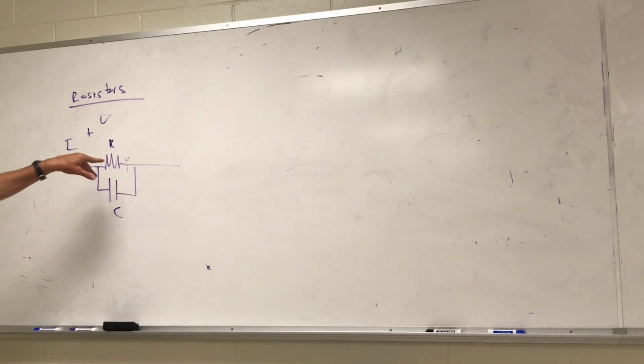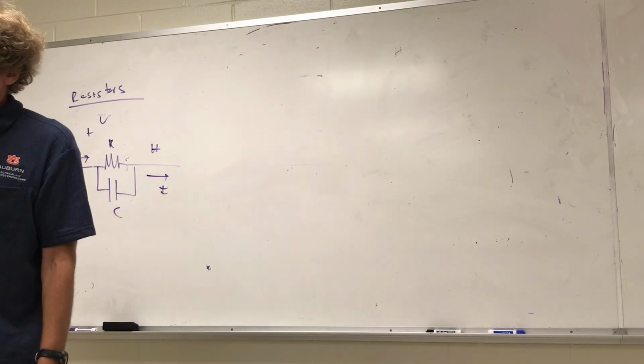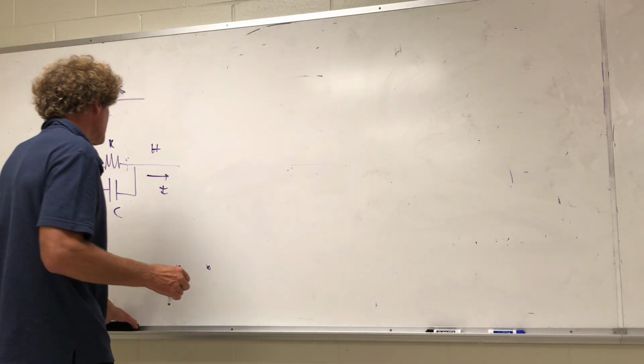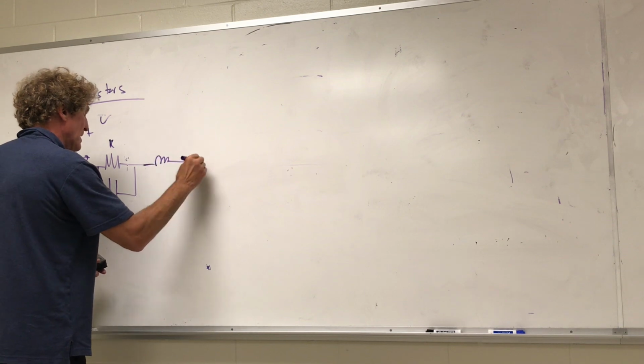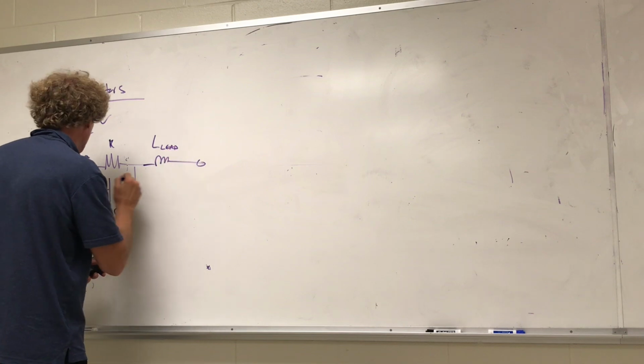The resistance is the main thing that's going to limit current flow in the straight wire. But anytime that you have a wire and you have current flowing in it, you have a magnetic field around it. You have both internal and external magnetic field. Anytime you have magnetic energy in a system that is not propagating away, that can be considered localized, then you have inductance. So now we're going to have an inductance. And what they usually do, almost always, is say this inductance will have the symbol L, and the subscript will be LEAD because it's for the leads.